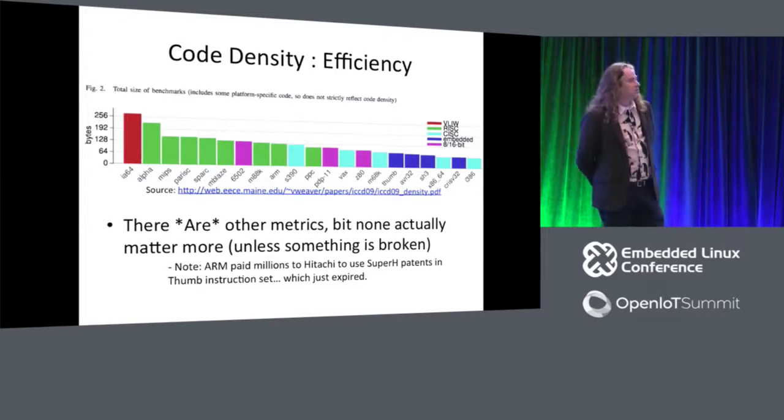You load one 32-bit word every 2 clock cycles, and away you go. You have an SMP system, you load one 32-bit word every single clock cycle. If you have cache controllers in the way, you might get 10% bus utilization on the outside. That's pretty good. It leaves a lot of DDR memory bandwidth for other things. So this is an important point when you look at what are the metrics for a processor at this level, right?